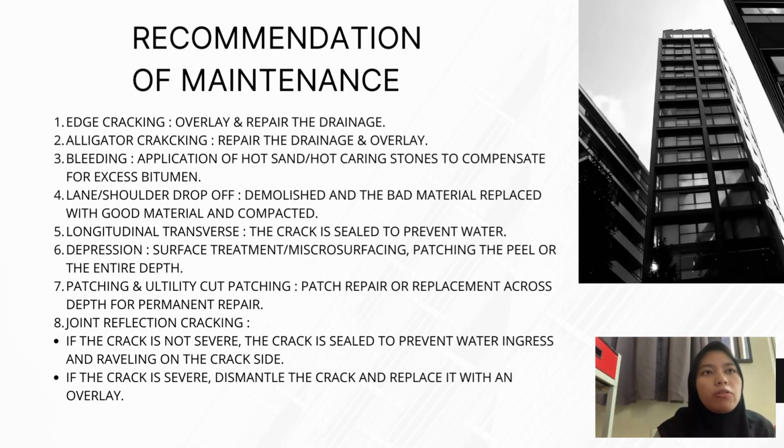For the recommendation of maintenance, we get a pyramid work from the survey before. For edge cracking and alligator cracking, we can do the overlay and repair the drainage. For bleeding, we can do the application of hot sand or hot coated stones to compensate for excess bitumen. For the lane shoulder drop-off, we can demolish and the bad material replaced with good material and compact. For the longitudinal and transverse cracking, the crack is sealed to prevent water.